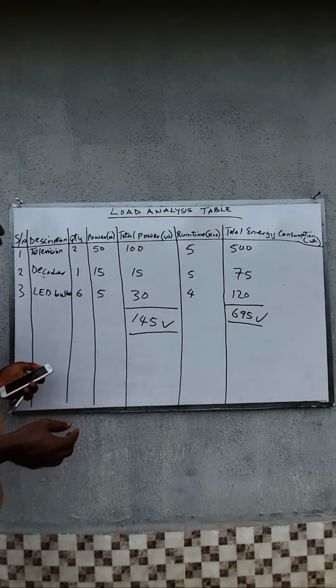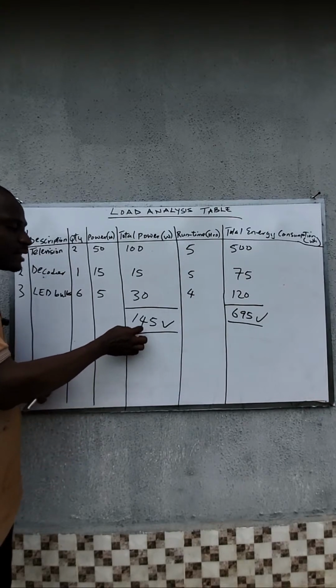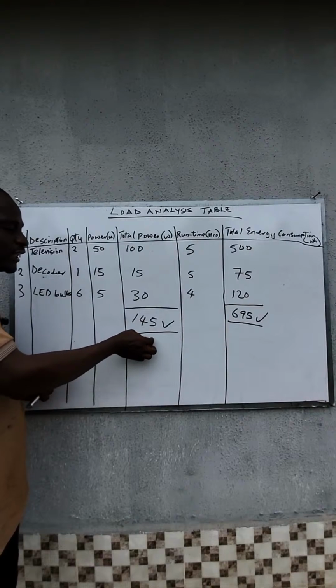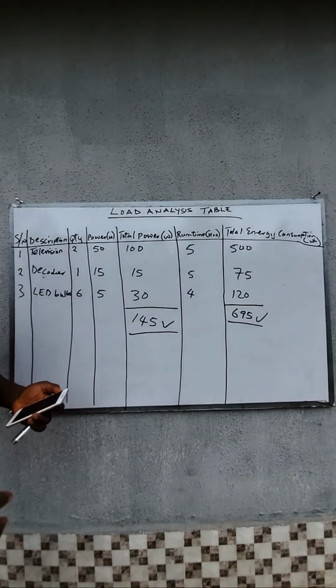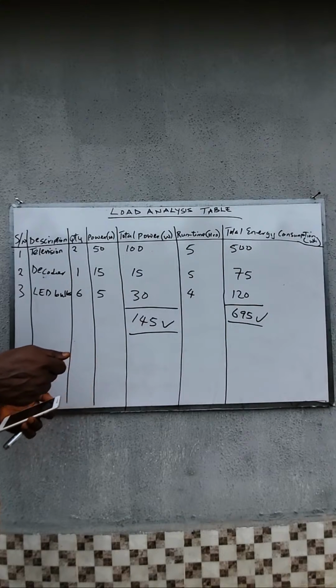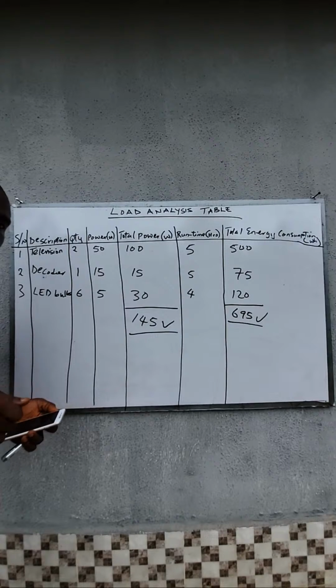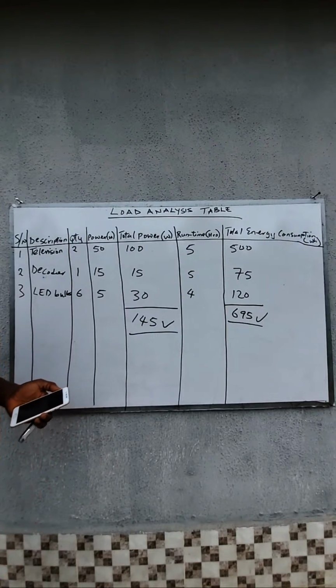So if you carry an inverter that is rated maybe 500 watts or 300 watts, it will not be able to handle that starting power. If you connect that refrigerator to the inverter, once you switch it on, the inverter will shut down. It's telling you that the load is higher than its maximum carrying capacity.